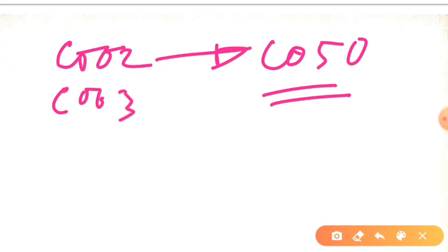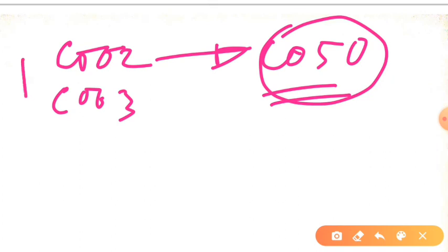If we did not use the jump instruction, or did not jump to the memory location C050, we would have fetched the next instruction from the memory address C003, and then onwards the next instruction from the next memory location. In this way we would have progressed.